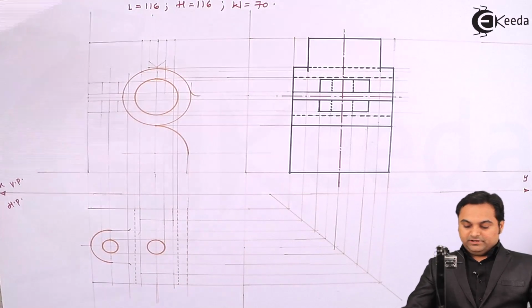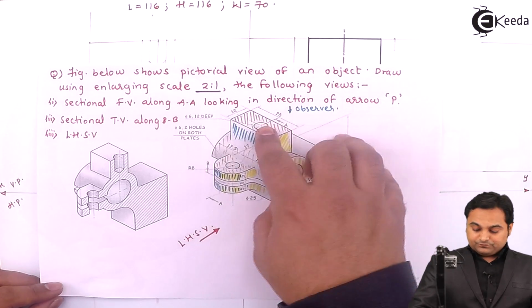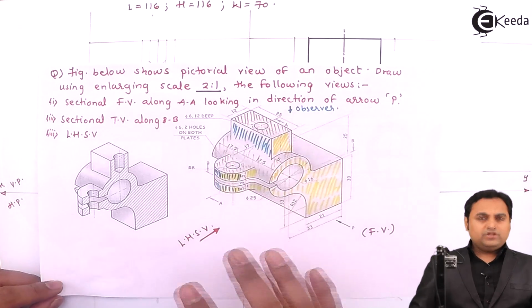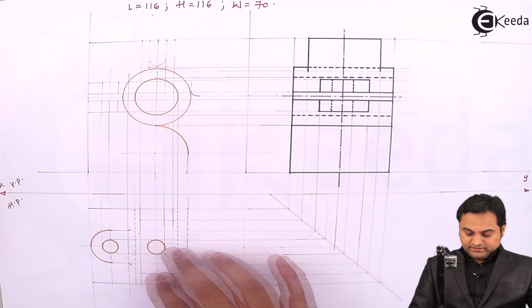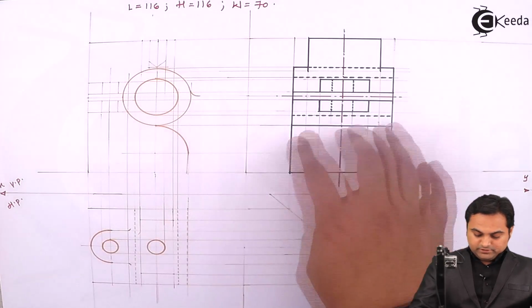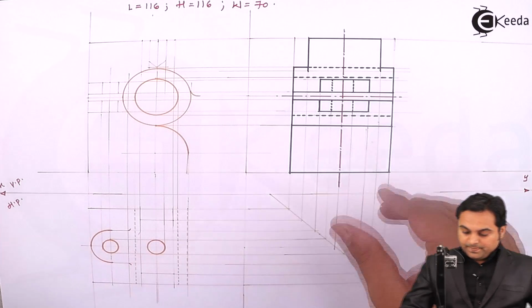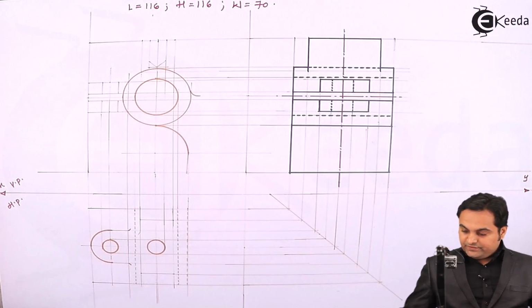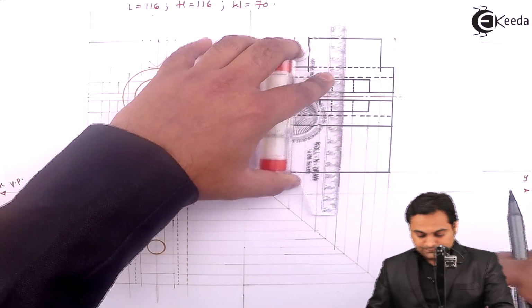Then, when reaching up till here, I can say that even inside this rectangular surface, there is a hole which will not be visible from the side, so it has to be hidden. So, getting this hole, it is onto the same level because both the holes are having the same diameter, which is 12. So, it will be projected up to the rectangular surface.